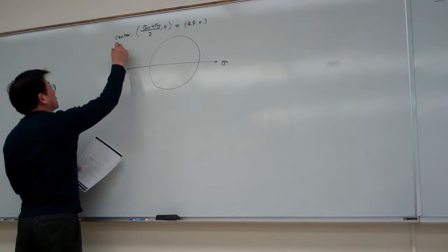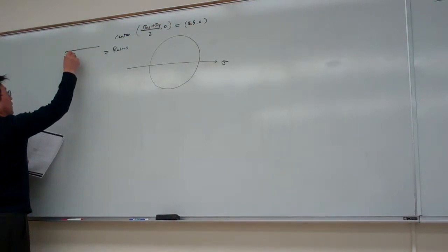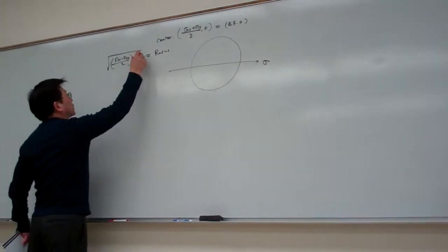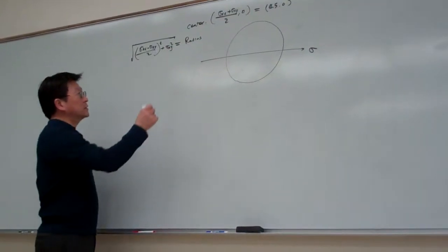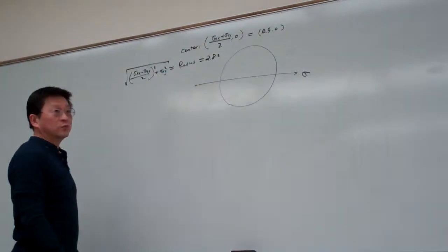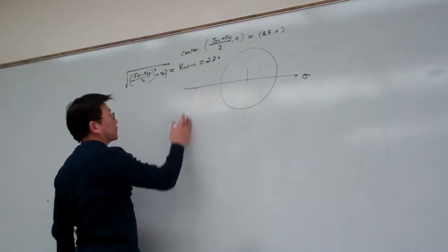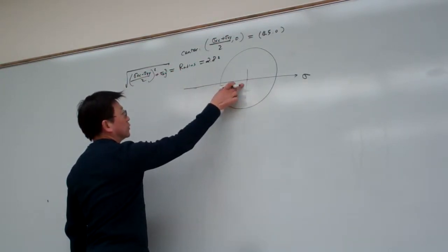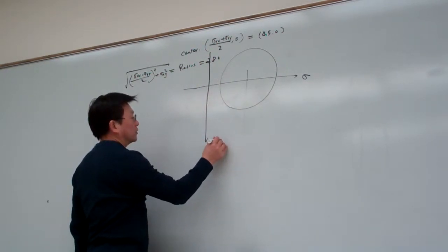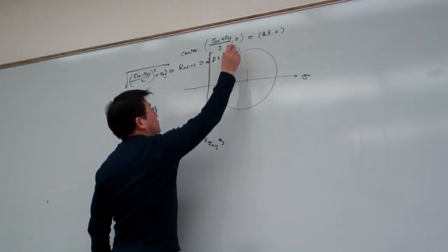And also we determine the radius. If you remember the formula, it is the square root of sigma xx minus sigma yy over 2, squared, plus sigma xy squared. That is the calculation of the radius, and for this one we've calculated 2.82. From here we can precisely locate. From the center to the vertical axis is 4.5, radius is 2.8. So here I can precisely locate, and this is sigma x with such annotations. Okay, and this is sigma y in these notations.